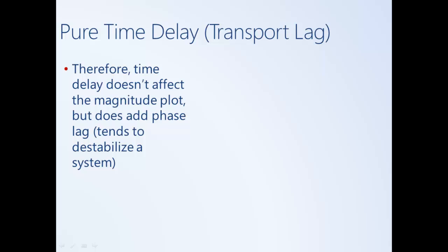So when you add this pure time delay to the frequency response of your system, it doesn't affect the magnitude plot, but it does add phase lag.